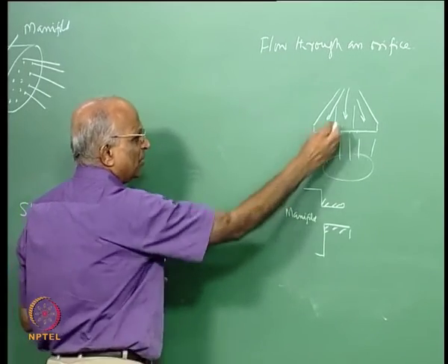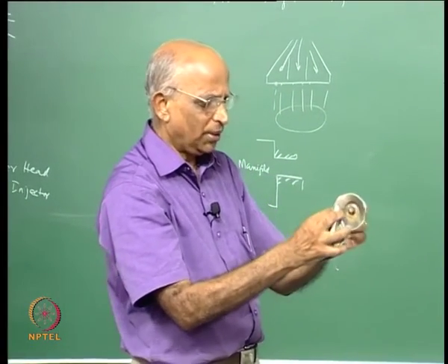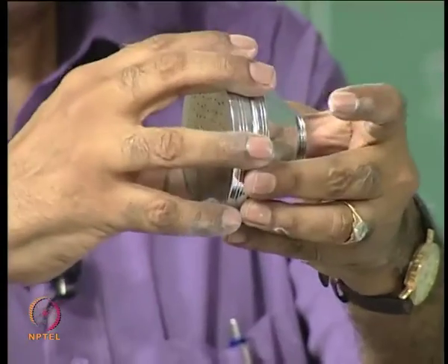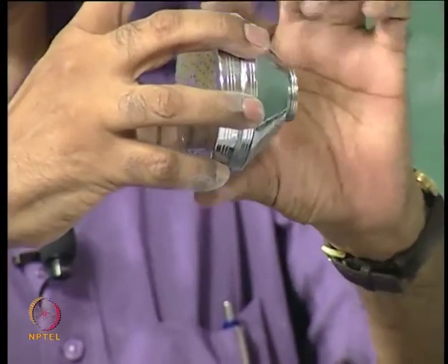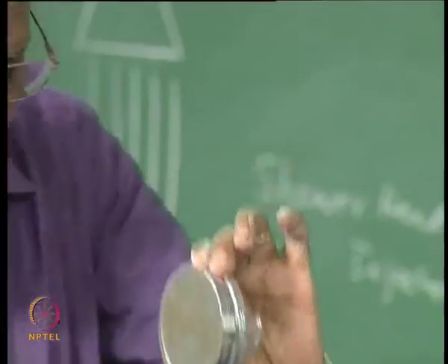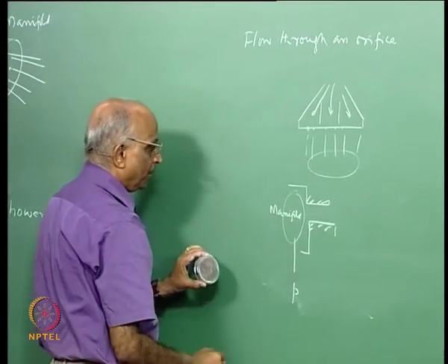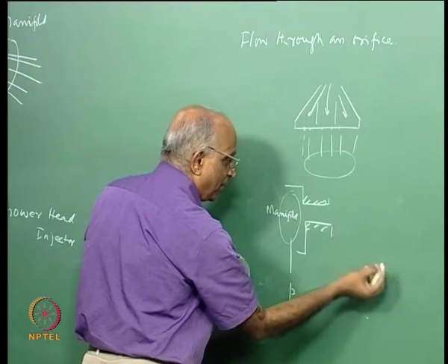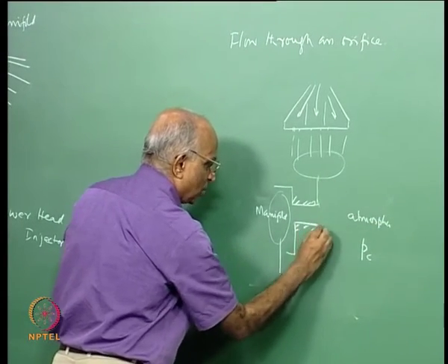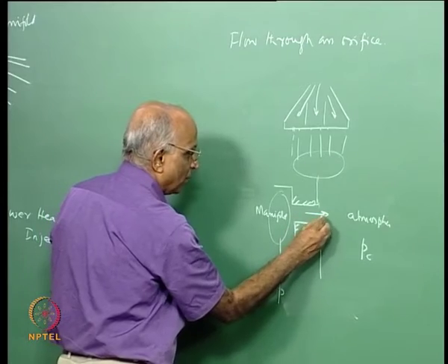See in the manifold, since the volume is large, let us again take a look at this. I deliberately brought this because you are supplying water through this particular hole here, it collects in this particular manifold here, that is, in the region in the chamber preceding the orifices. Therefore, the pressure in the chamber is the supply pressure, the velocity is almost 0, and then the water squirts out through these particular holes. Therefore, in the manifold I have a region of supply pressure P, and where does the liquid get supplied? It gets supplied, when we are taking the bath, into the atmosphere. In the case of a rocket, it gets supplied into your chamber pressure because the orifice fits into my chamber, and therefore I have chamber pressure here, I have the supply pressure here, and I am interested in finding out the flow through the orifices.